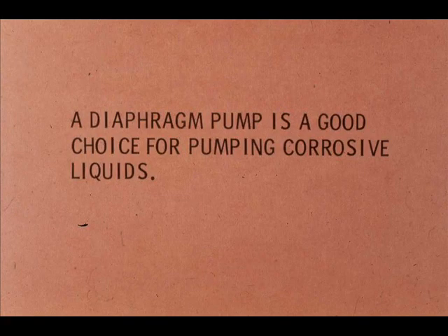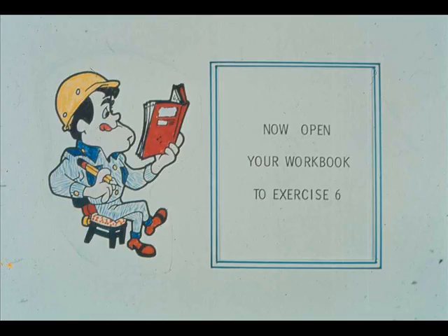A diaphragm pump is also a good choice for pumping corrosive liquids. Liquid does not touch and therefore cannot corrode most of the pump parts. Only the diaphragm, valves, and liquid chamber need to be protected against corrosion. Now open workbook number 2 and complete exercise 6.